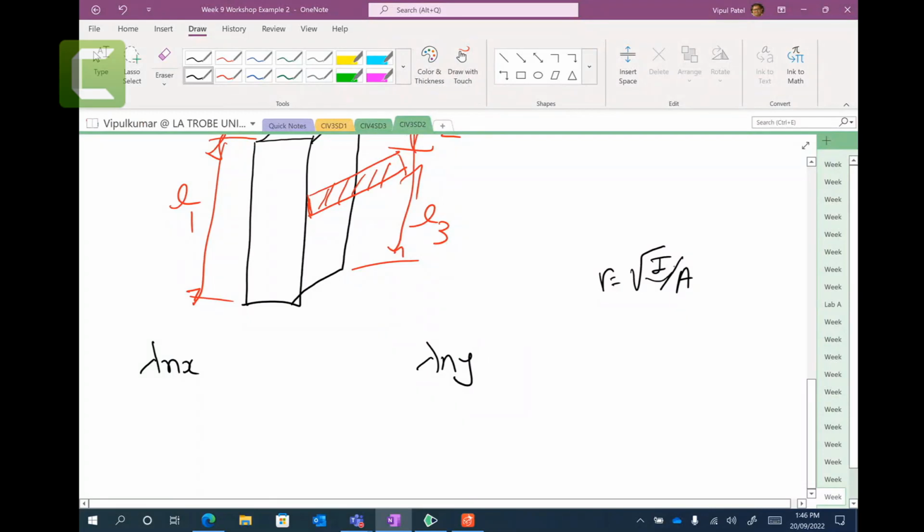So it's about the resistance about the moments, the resistance about the bending, right? So the smaller the value, the higher the chance of getting buckling, because there is small resistance. Make sense? Which bigger number? Lambda n? Yes, the lambda n is correct. But for this one, the smaller number is worse. Does it make sense, or kind of? The question is, how does a smaller radius of gyration make it worse?